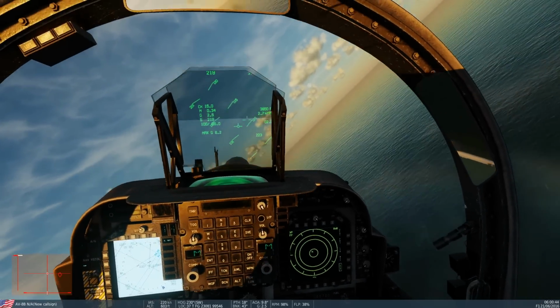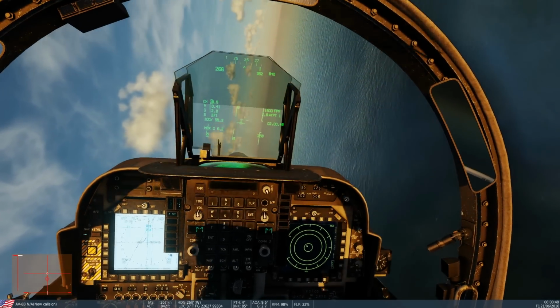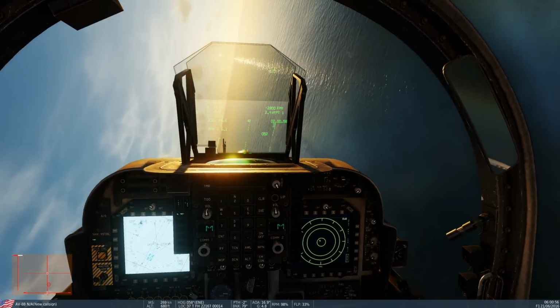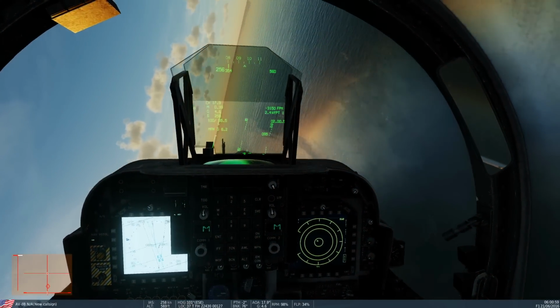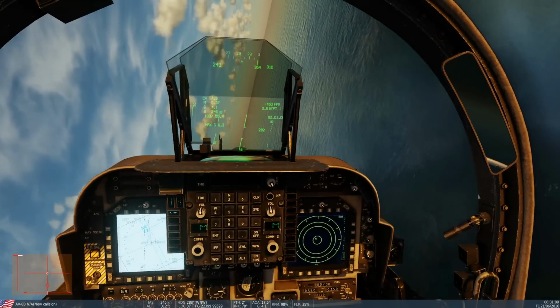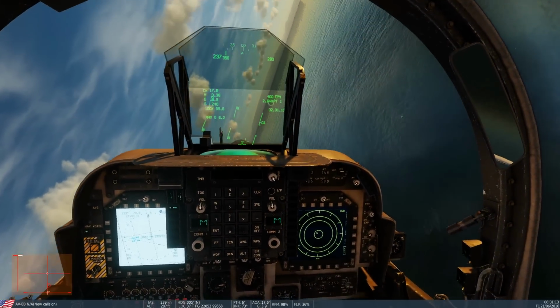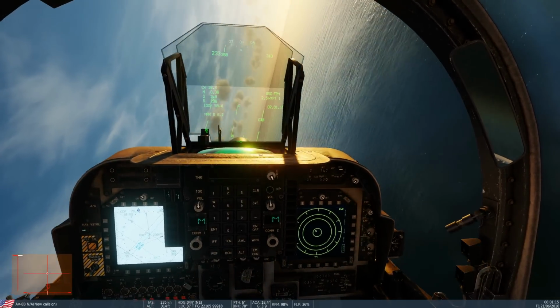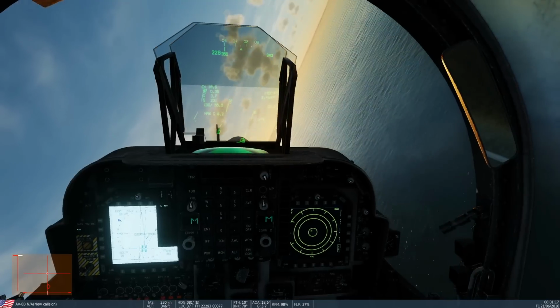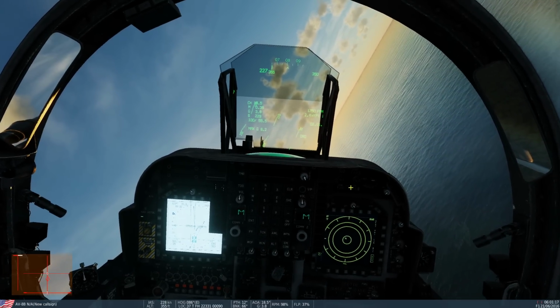See if we can get right on the edge of that stall. You see the speed suddenly plummet uncontrollably. So bear in mind that throttle is a constant. The only variable here is my aft stick. It's really going to be hard to quantify. I think that's 17, 18, 18. Yeah, it can't go any more than 18. It stalls at 18 and a half. Let's go and try it with vectored thrust.